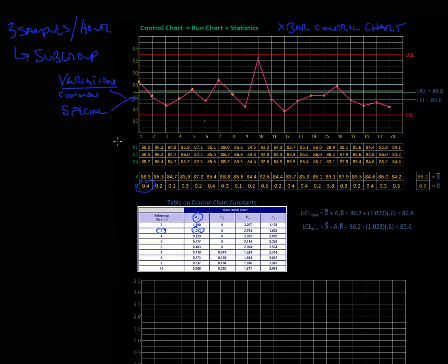So you have a certain level of variation that's inherent in the process, but when that variation exceeds our control limits, statistically speaking, it's probably due to a special cause of variation. So we have common or ordinary variation, and then we have special cause variation. It's the special cause variation that leads a quality engineer to conduct an investigation.